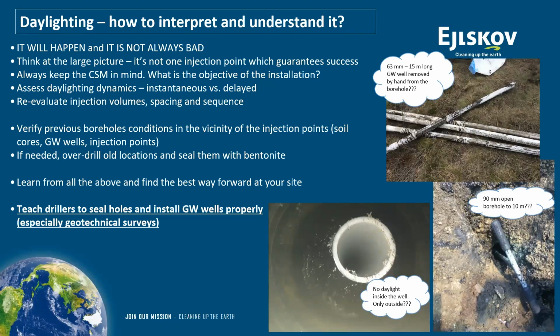So what we try to do is to think, how can we adjust injection volume, the spacing, the sequencing of the intervals? Do we have to skip some intervals? But again, we need to know where the mass is so that we can always try to target that mass of contamination as well as possible. And that's the experience we have from hundreds of sites performed, where, for example, in some of the cases shown here, personally, I've been removing a 15-meter long well from an open borehole.